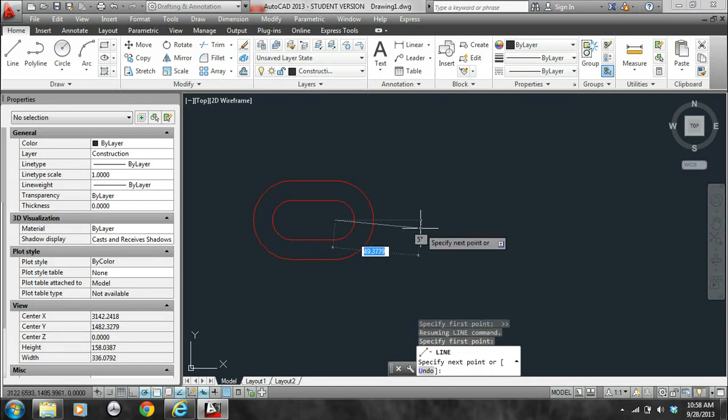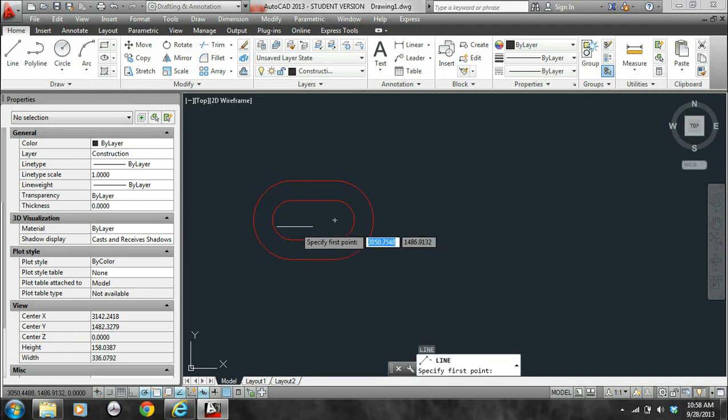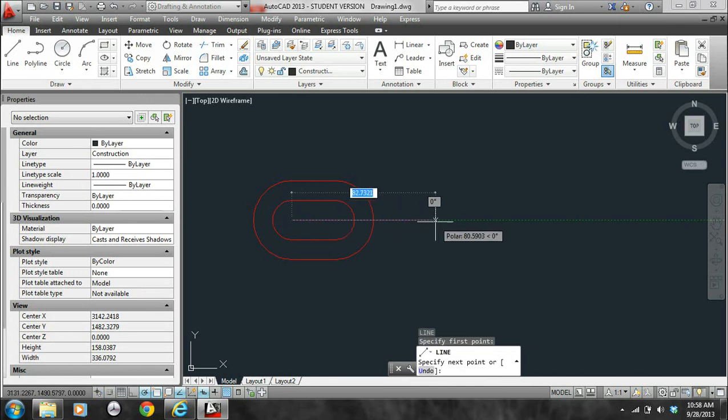And now we're given a dimension of, oh goodness, we're actually not given a dimension from the center of the pad directly to the boss. We are, however, let me try this. Let me draw a line from the center over here, and you can see that we're given a dimension of 148 to the center, the lower portion of the pad on the right side of the object.